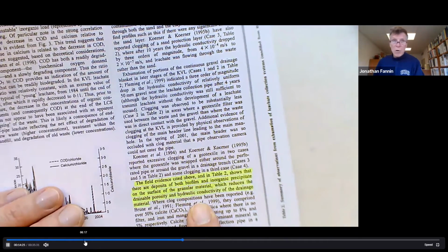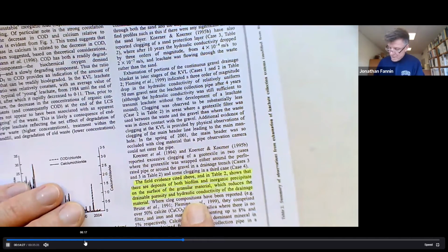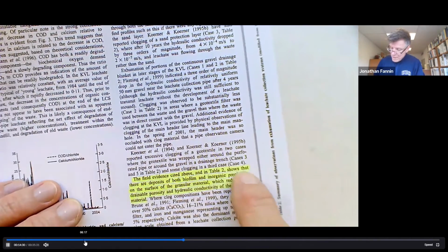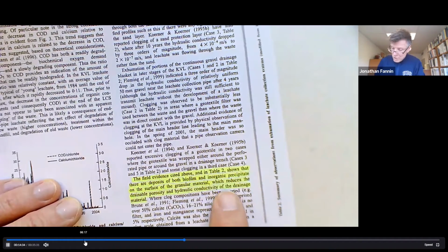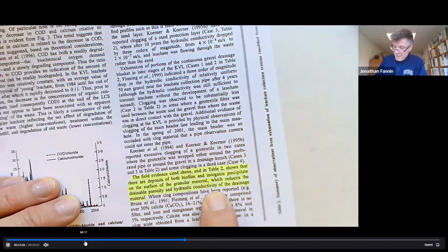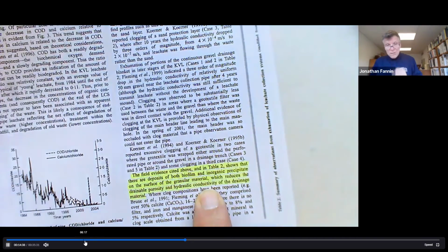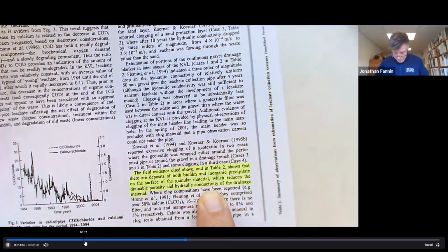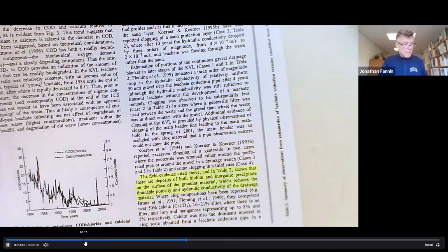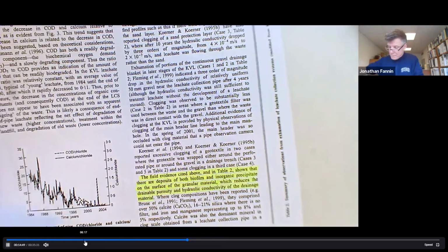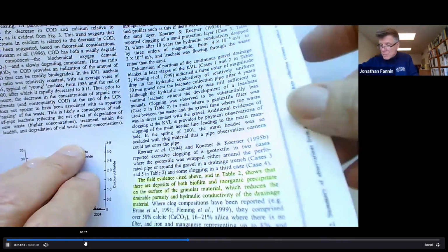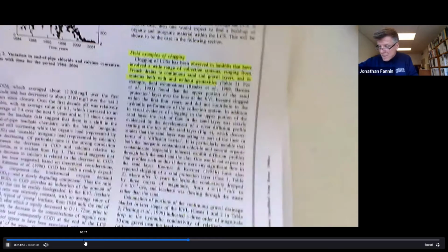So we want to try and have something that its primary job as a leachate collection system is to be permeable and remain permeable. And the argument is that's an important function for the durability of the barrier below it. Otherwise, it's sitting in a pond of this leachate. But the action of the biofilm growth and the precipitates is to compromise the porosity and thus cause the hydraulic conductivity to lower. Okay, and if we follow this through, then turning to page 639.